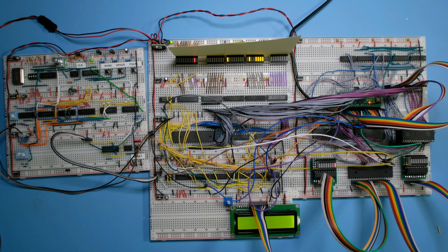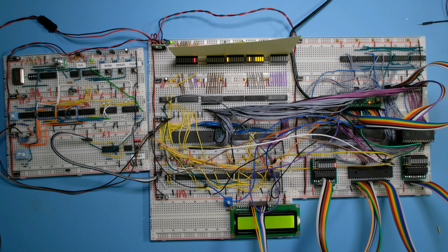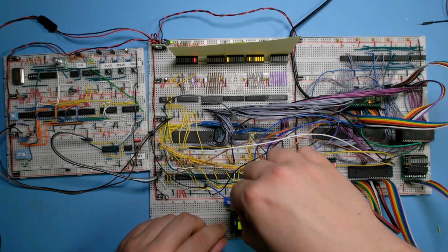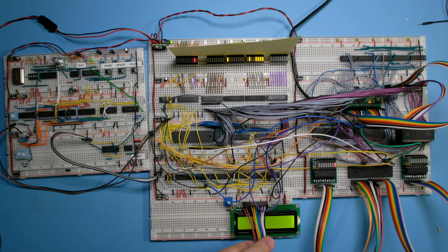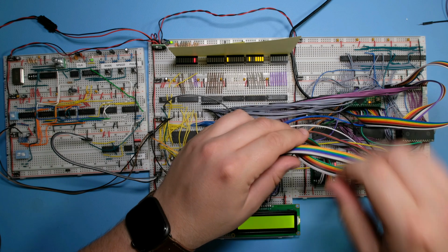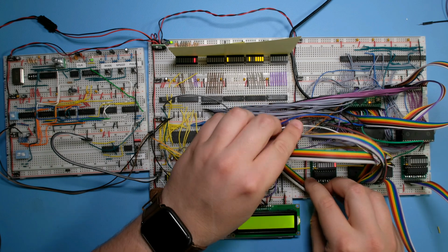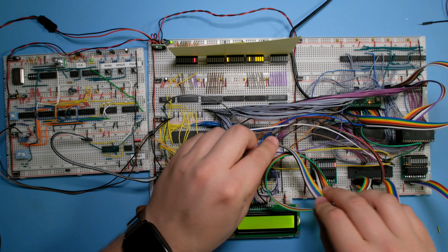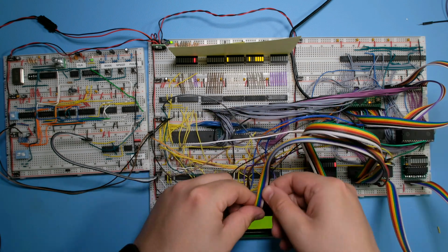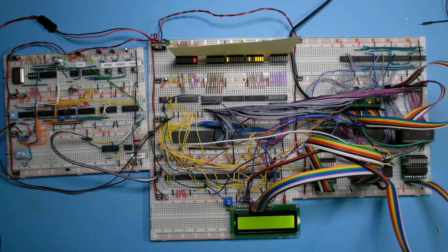And then we need to bring in the control signals. And so these are the 3 least significant bits of port B. And those connect in this way. So I need to find a way for those wires to not be in front of the camera, but also that we can see the LEDs that are here. So let's go and write some code for the display.